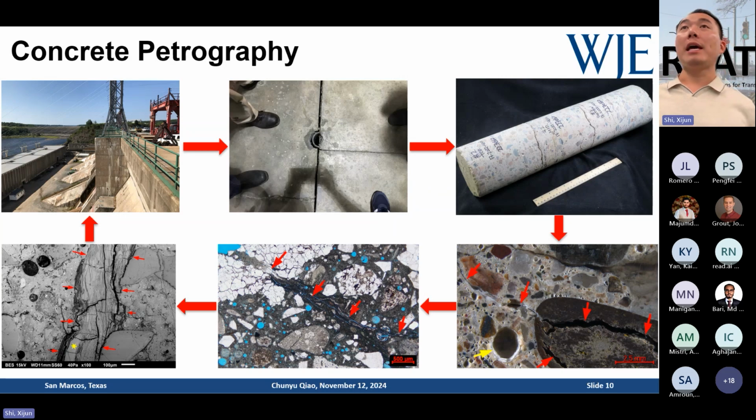Also, we want to know the nature of the rock. So we want to know what are the reactive components in this concrete. Only based on the color on the left section, that cannot give information to determine the aggregate type in this investigation. So then we want to use the thin sections, as I said. The thin section picture is in the bottom middle image.